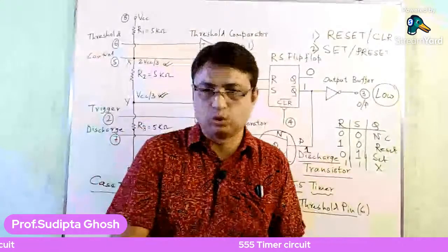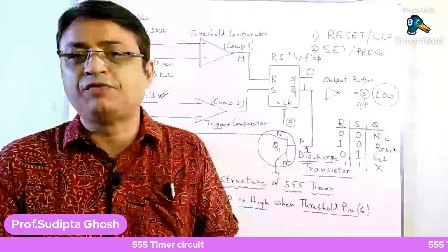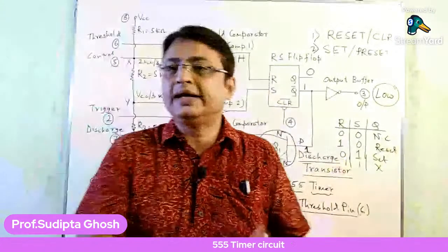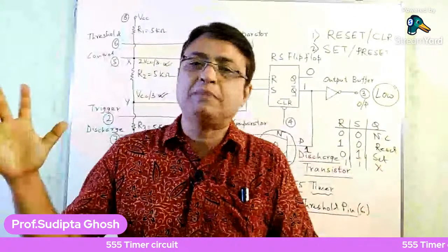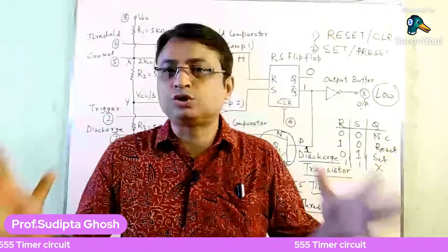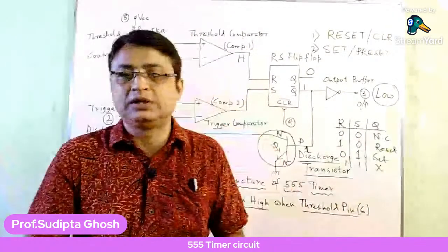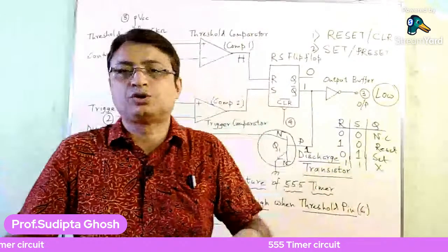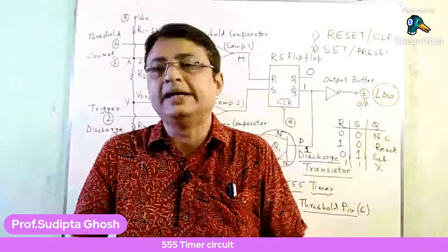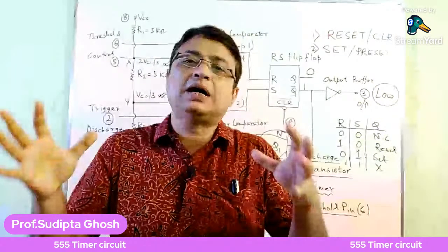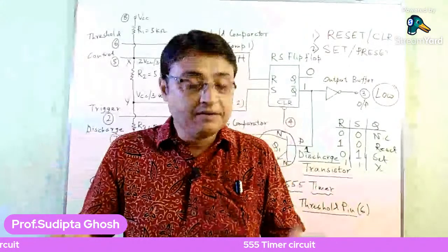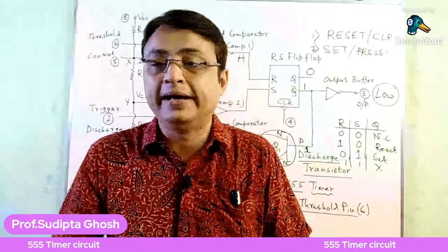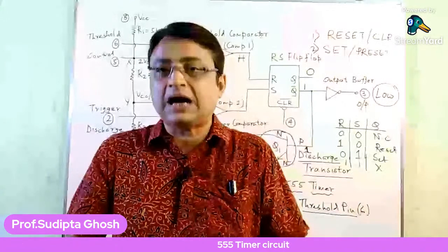The two voltage sources we apply in a transistor circuit, one may be emitter base and the other collector base, the input and the output voltages, are always used to bias a BJT. So if both of the voltages are in the reverse bias mode, the transistor will be in the cutoff state. So the answer cutoff is not right here.